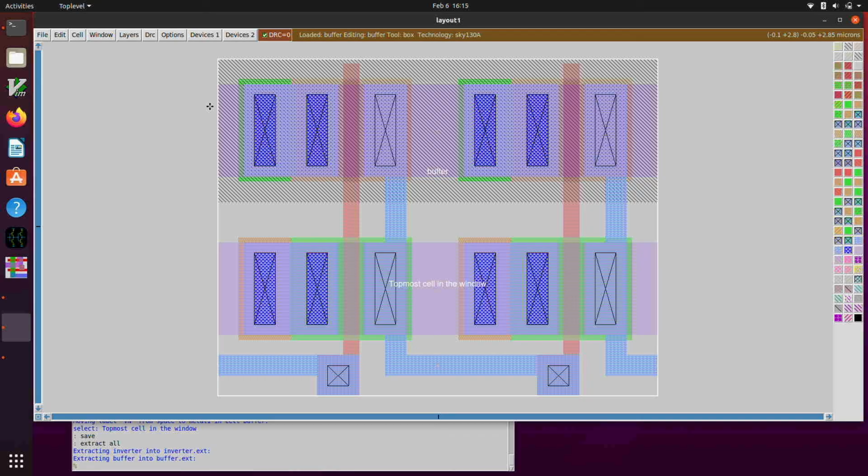And if we wanted to, we could extract parasitic elements in our circuit representation that would represent like the parasitics of the interconnects and things like that. And then we run a command called X to SPICE to turn that extraction into a SPICE netlist.